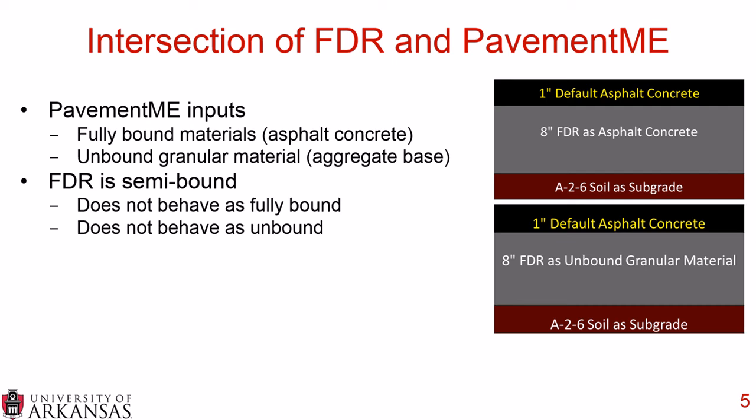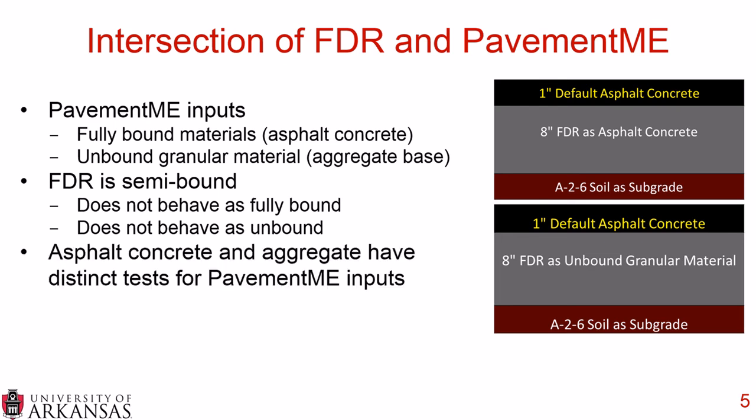However, FDR isn't asphalt concrete and FDR isn't unbound granular material. So if you're doing a pavement design with PavementME and FDR is one of your layer materials, it doesn't really have a home in PavementME currently. However, PavementME does have distinct tests that need to be run for asphalt concrete and for aggregate.